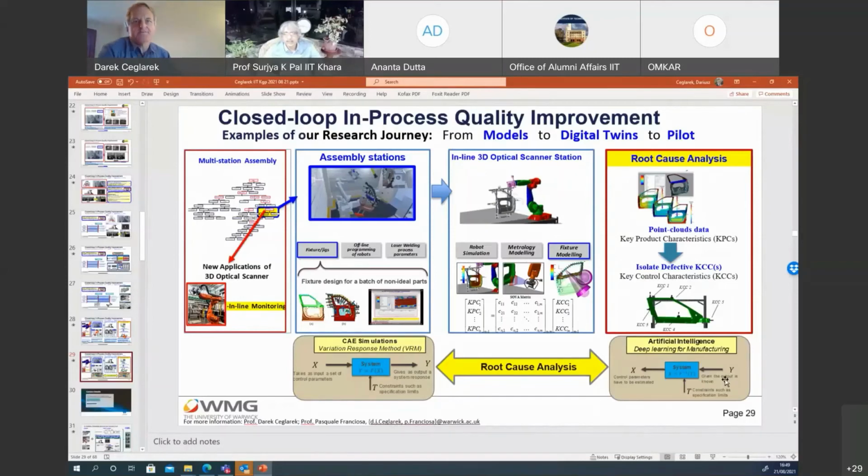Yeah. One more question is that you have talked about the gap identification for the welding, and based on the gap, you are trying to optimize the weld parameters. Now, when we talk about the weld gap, are you only measuring the in-planar gap or the out-of-plane gap? That means, are you capturing the image only from one side or from, let's say, multiple sides, depending on the gap in the X direction and the Y direction?